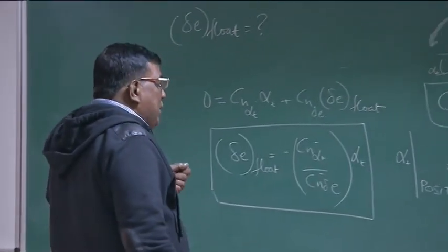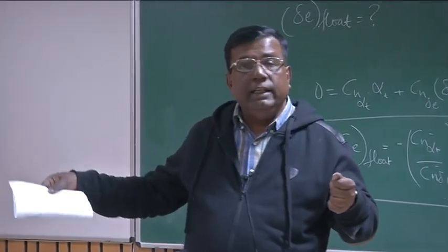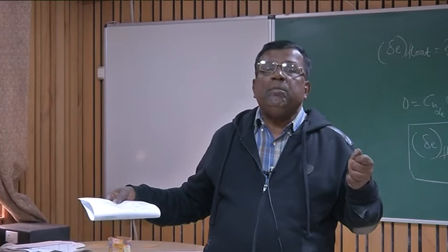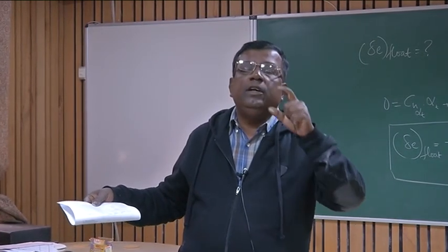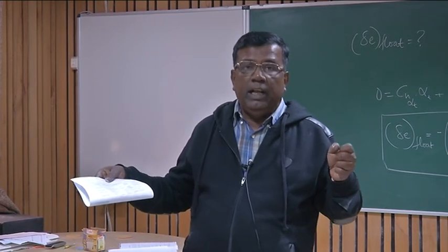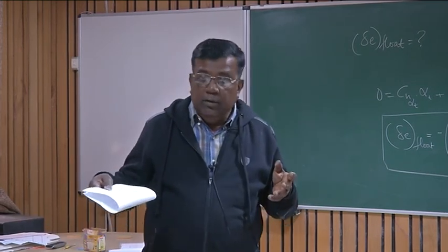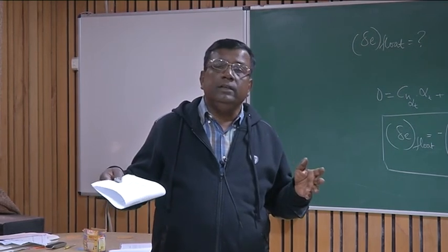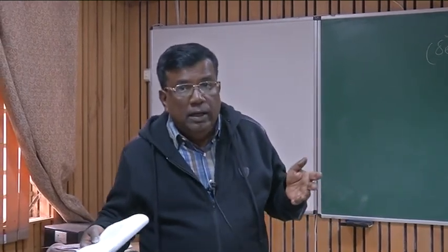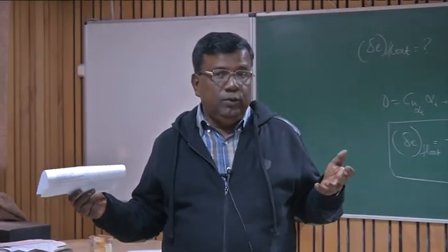Second thing, if the pilot has to put in his stick force, the elevator will turn like this. So one should be smart enough to know that the pilot should put in that much effort to cover only the remaining difference in angle, because the elevator by itself will already float by some degrees. Let's say 5 degrees is the aiming angle for the elevator, and by float it is going to 3 degrees. So the pilot effort will be only for 2 degrees, because anyway it will float. But the only problem in modeling is that this floating angle changes at different alpha t. So it becomes really complicated.